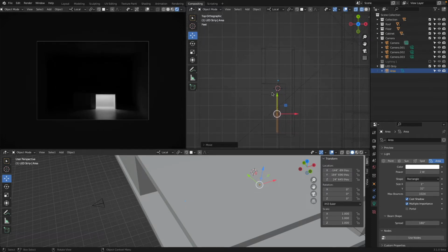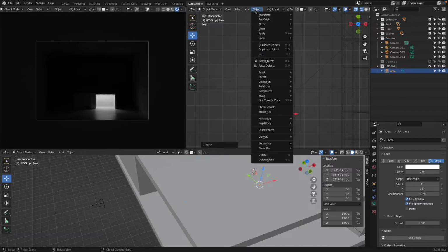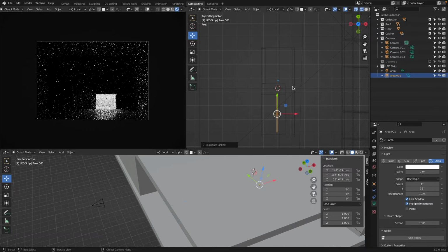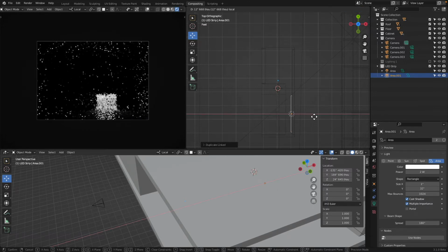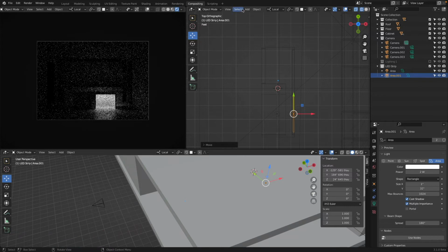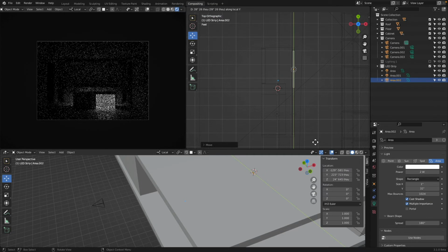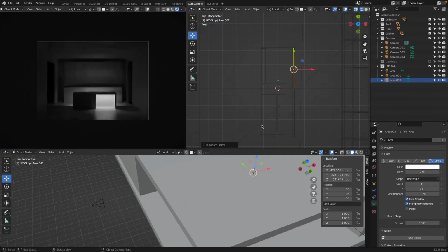I would like this LED to be used too in multiple locations. Okay. Linked, and then I press escape. Then I have a copy, right, and then I move this to the back. Do this again. Linked, I can press Y and move this along the Y axis. When you make a linked copy, it creates a copy and you go right into the move command.